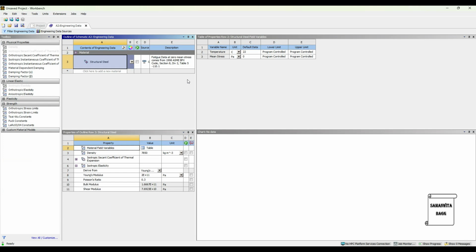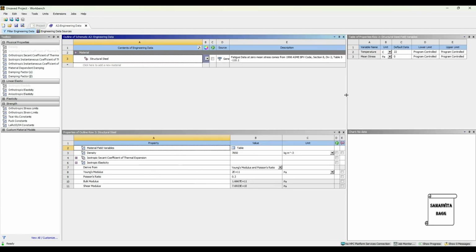Various types of materials used for manufacturing of globe valve are carbon steel, alloy steel, stainless steel, brass, bronze, cast iron, nickel-based alloys, titanium alloys. Now out of this, we will be using stainless steel, brass and bronze as the three materials for analysis, and we will do a comparative analysis of the three.